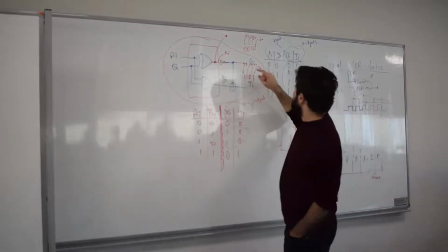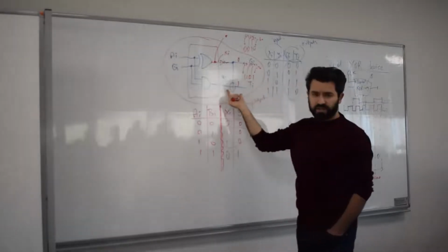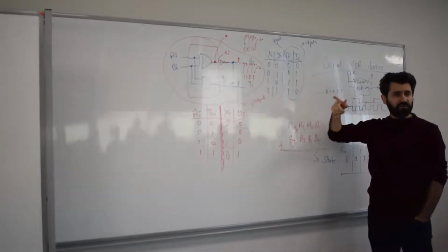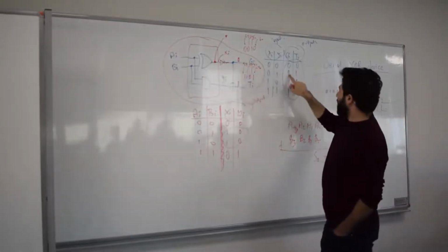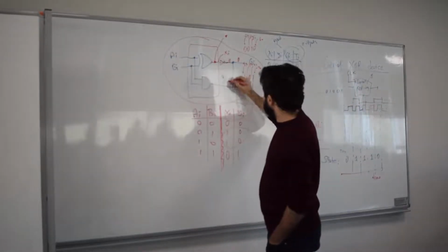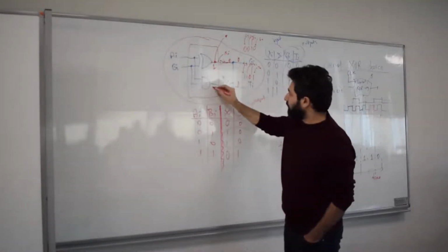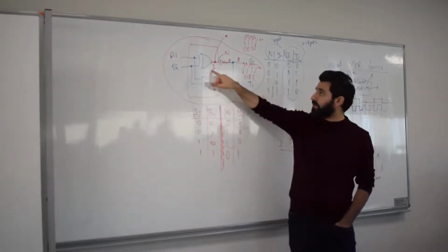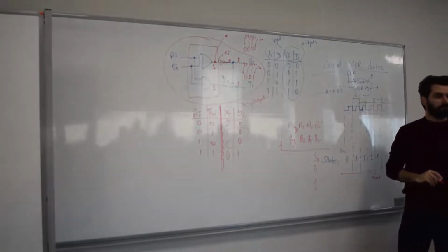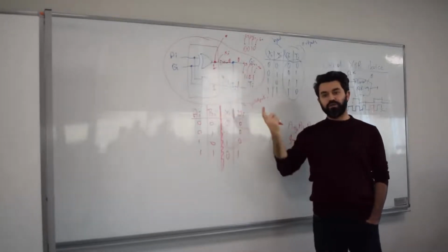What does that mean? That means if G0 is 0 and T0 is 1, then you reverse that. You don't need to memorize anything, by the way. You go to this truth table, which I've given to you. That means 0, 1. So I have got 0, 1 here. What's the corresponding input? 0, 1. So it doesn't really change anything. This is 0, this is 1. And there's a NOT gate, so that means this is 1, and this is 1. Good. I figured that the XOR output here, S0, is actually 1. I just walked backwards using this idea of reversibility.